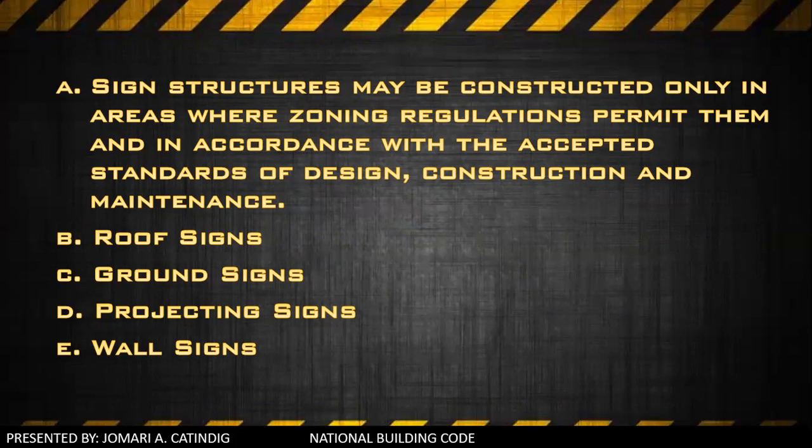Letter B, the roof signs. No signs are to be constructed, attached to, installed, or fastened on the rooftops of wooden structures or buildings, or structures with wooden roof framing. Adequate provisions for grounding metallic parts of roof signs exposed to lightning shall be provided, and installation of warning lights or obstruction lights for air traffic shall be installed where applicable.